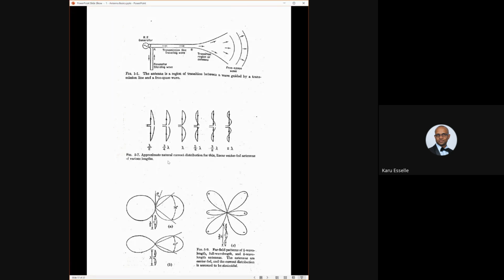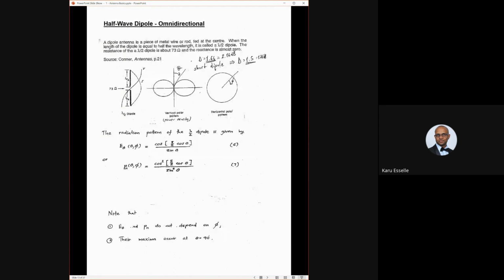Okay, and the other simplest antenna is a loop. Now this is more about the half wave dipole. Same thing. This is quarter wavelength. This is quarter wavelength. Input impedance is almost resistive. Input resistance is 73 ohms. Input reactance is almost 0. I already mentioned all these things, right?